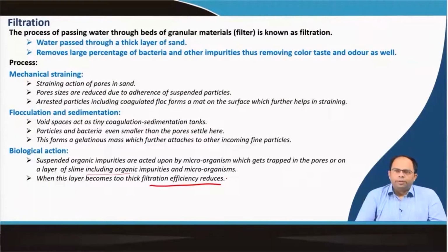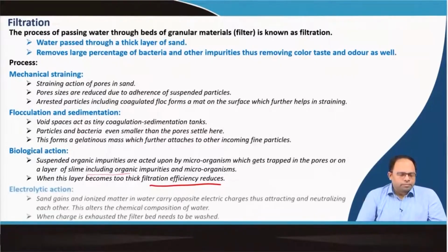and finally the filtration efficiency also reduces. In addition to all this, we also have electrolytic action, in which sand grains and ionized matter in water carry opposite electric charges, which helps in attracting and also neutralizing each other. This alters the chemical composition of water to some extent.